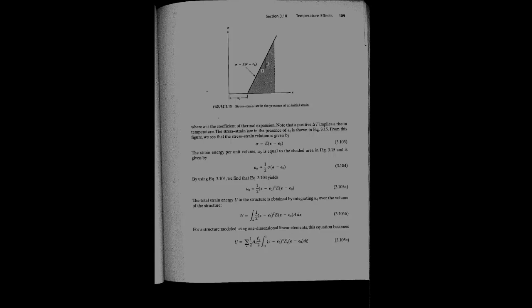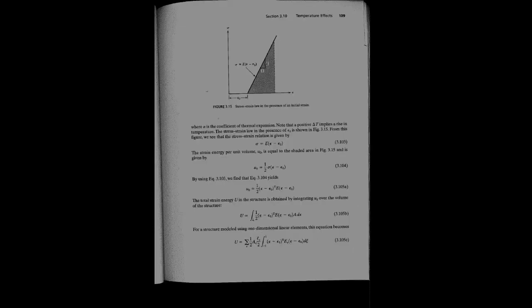But as soon as I start pushing it back, or restrict it in a way that it can't expand, then stress evolves. And this stress component can be quite dramatic. As a matter of fact, lots of mountains are carved open because water goes in between cracks, freezes, and cracks open the mountains. So those stresses can get quite large. So it's an important consideration, but luckily it's quite easy to relate, because this is just related by alpha delta T, where alpha is your expansion coefficient for your material. Okay, so that's a 1 over T kind of unit.